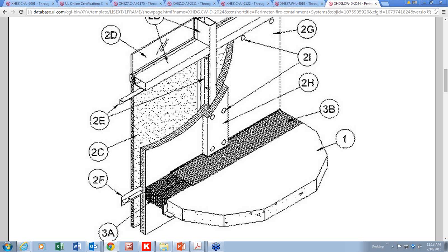So then you wind up with some kind of a fire resistance gypsum assembly, not as a fire barrier in the sense of the fire barrier used in the wall, but a thermal barrier between the flammable insulation and the exterior skin of the building, with all of those penetrations sealed as well, the way they should be.